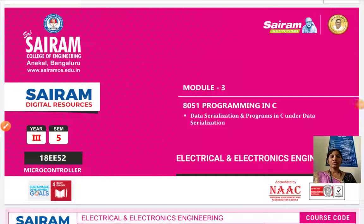Good morning students. Today we are going to see data serialization using 8051 C. So what is meant by serialization? Data can be sent bit by bit or as a byte of data, depending upon whether it is serial communication or parallel communication. Data serialization means sending a byte of data one bit at a time through a single pin of a microcontroller.